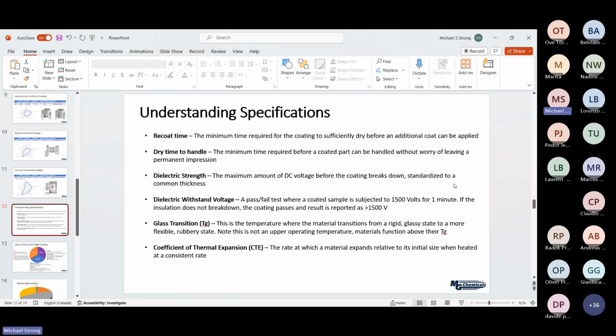And that's actually how you can detect these glass transition temperatures, because below your TG, your material is very stiff, so it's able to resist changes with respect to an external pressure. Whereas beyond the TG, now you have this softening, so it tends to expand a lot more.